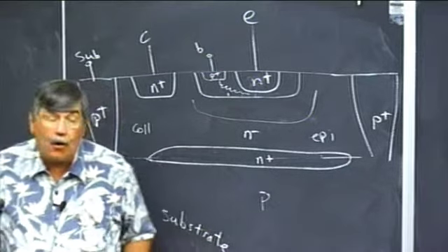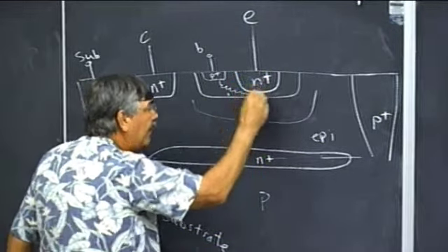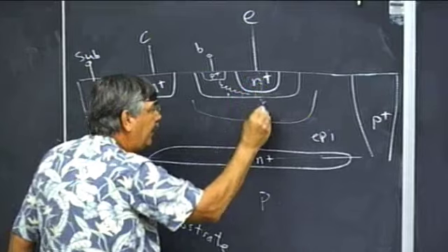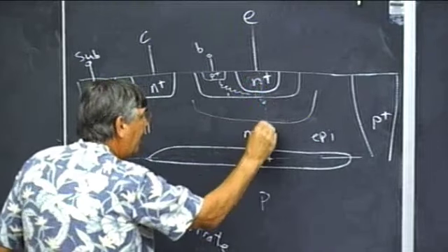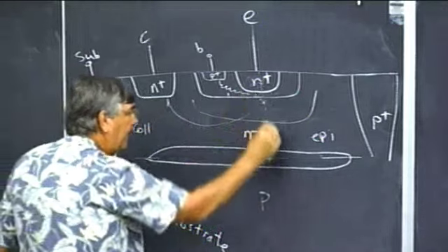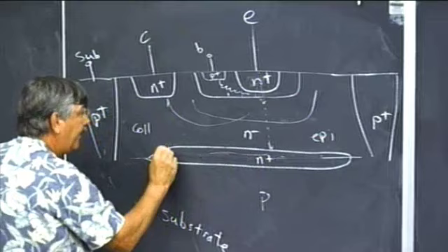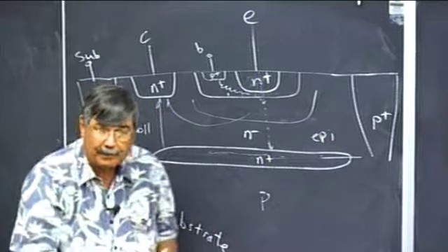If it's lightly doped, then we've got a lot of a path. The main path in the transistor comes right through here. The electrons go like this, and now they start figuring out where to go. Some of them can go down here to this epi layer. Some of them may go directly this way. Some of them can go down through here, way over to here through a very conductive path and back up, and that's why we had the buried layer.